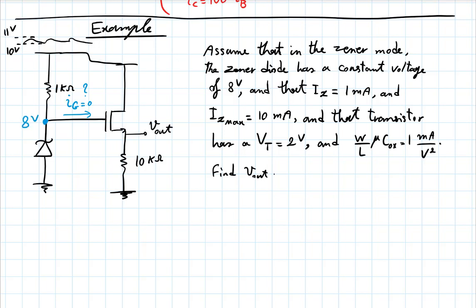That's the Zener voltage. As the input changes from 10 volts to 11 volts, does that 8 volts change? No, the Zener is modeled. We've taken a simple view of the Zener. What we are saying, in effect, is that the breakdown of the Zener is extremely sharp, almost vertical, so the incremental resistance there is negligible. And we can assume that that's 8 volts.